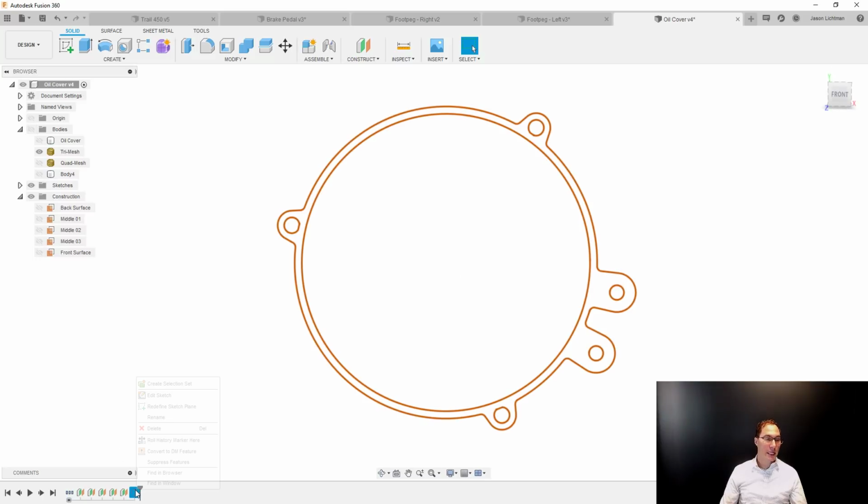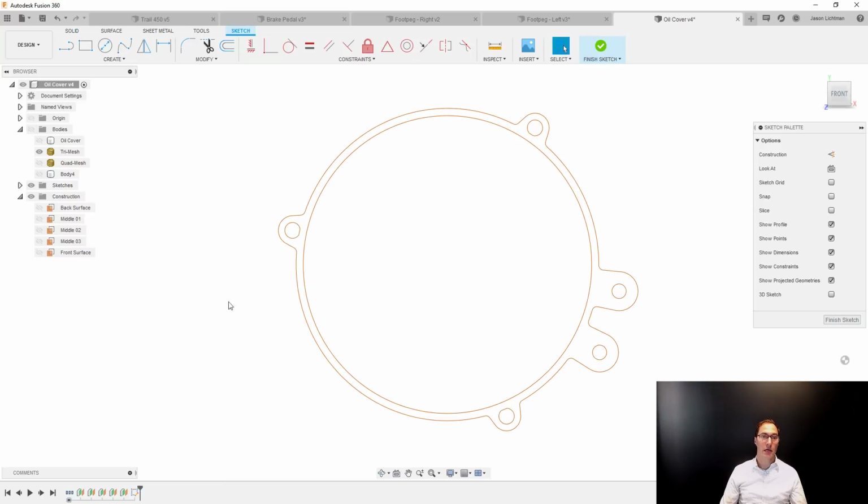We're going to edit the sketch and take a look at what's inside. What you're not going to see at this point is the ability to actually select this and extrude it. This orange version of a sketch is not really a full sketch. You can't select this and extrude it or revolve it or anything else. This is kind of halfway to the sketch you want.